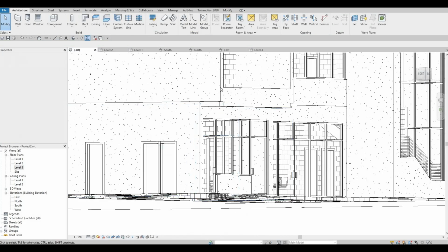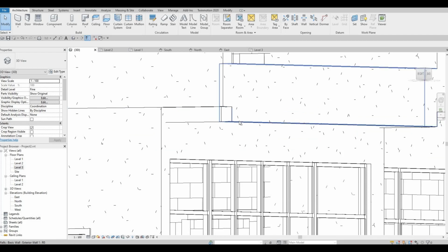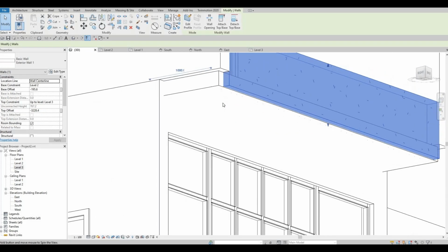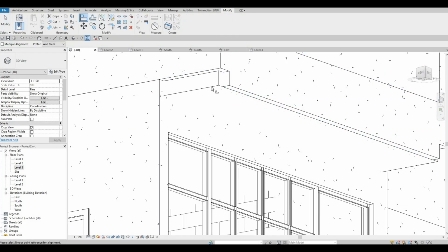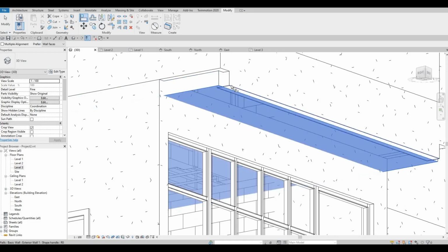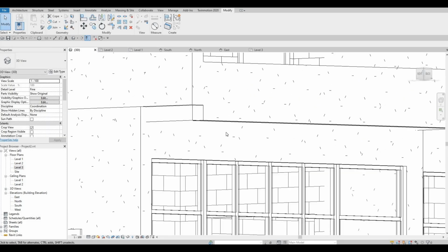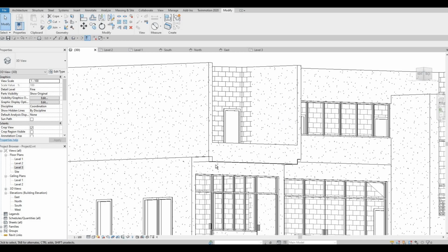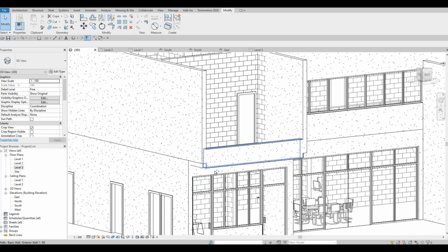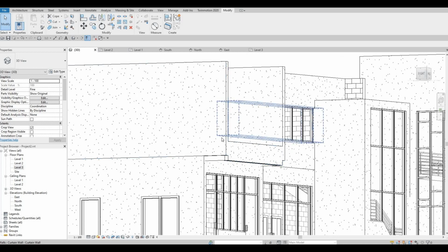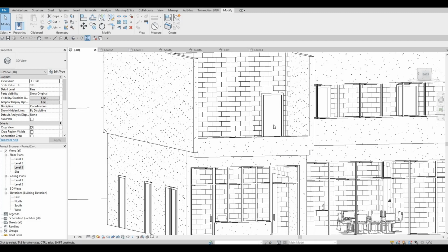And then once we do, I'm just gonna make sure that I align this all the way down. So I'm aligning this one like that, and then maybe we could pull more walls backward so that we could create this as an extrusion. I think it will be easier for us to do, especially since it has this design. So now let's do that.